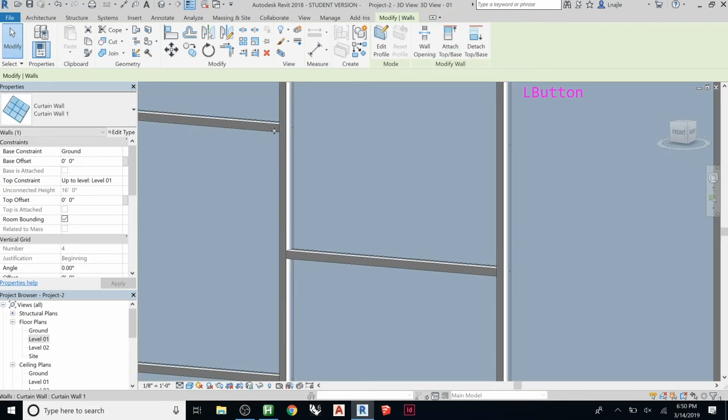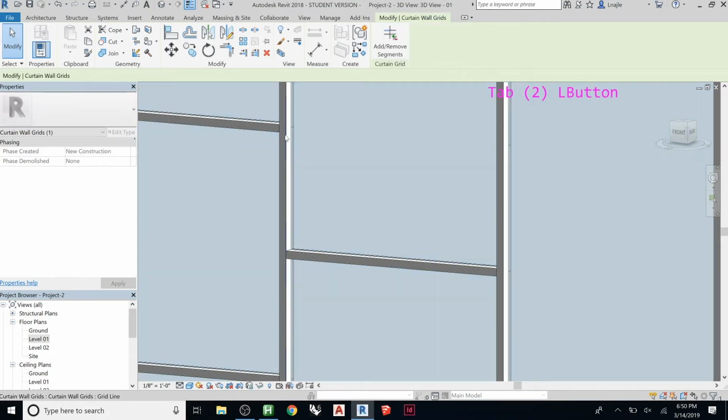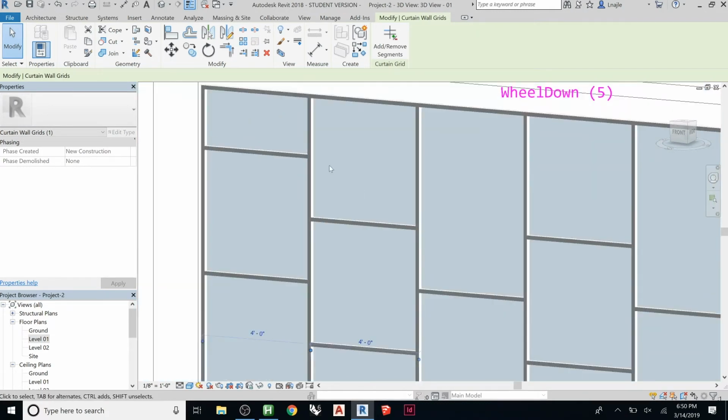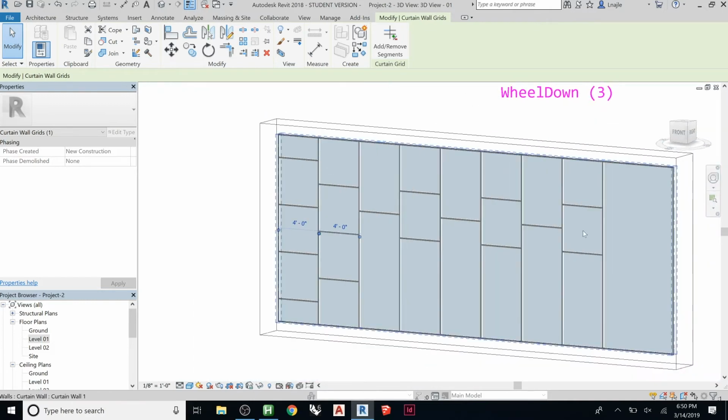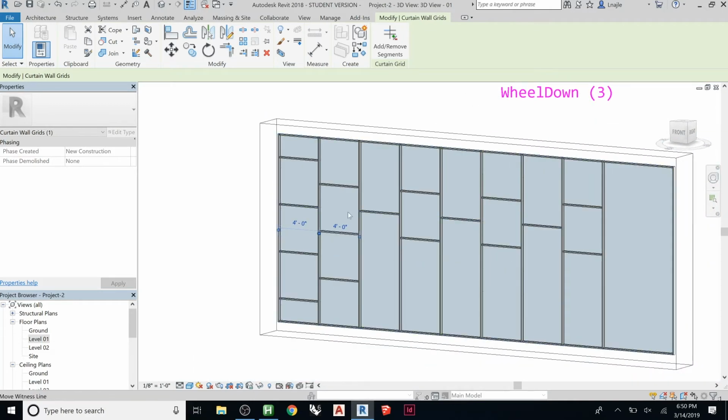I think you need to grab, so sometimes Revit will cut the mullion, and we don't have any that go straight across, do we? No, I broke all of them. But instead of stopping the horizontal with a vertical, you can make it go across, and then the other one can get broken, or you can make it look like they all join together. So that's how you adjust those settings.